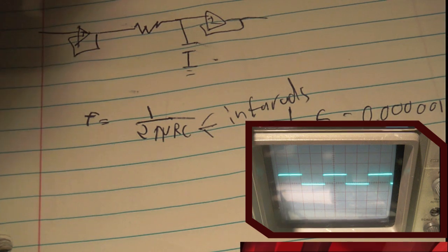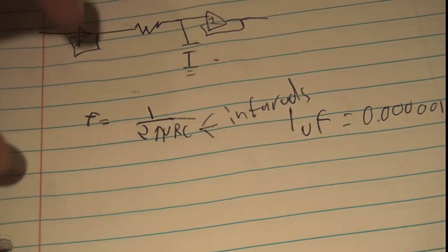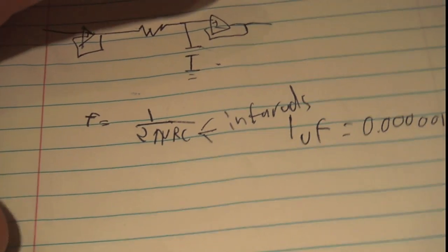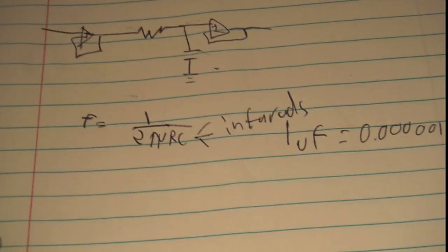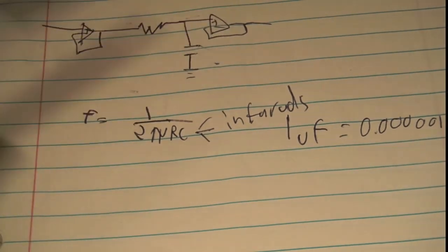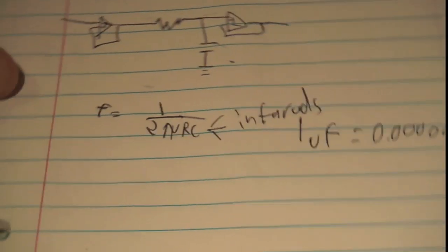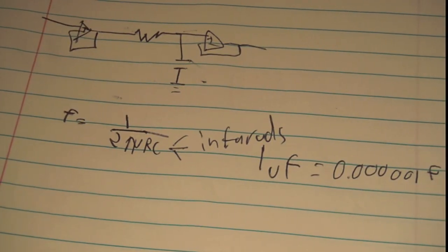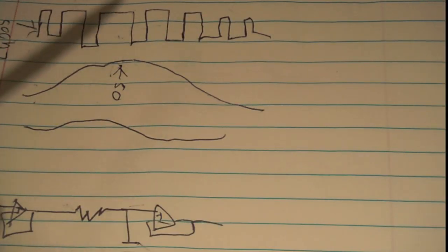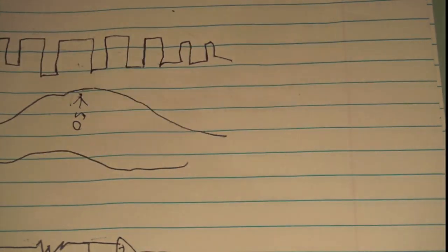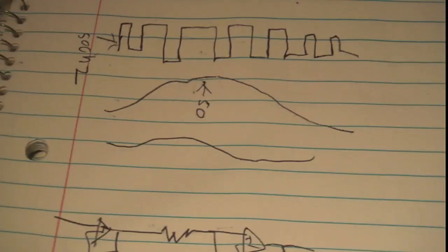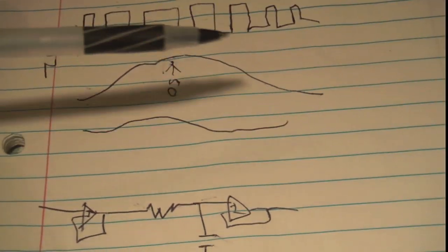So, I mean, that's very low. That's unnaturally low for a PWM signal. So that's going to make our job a bit tougher, but it's going to mean that I'm going to have to design better low-pass filters. So this probably won't cut it, but we'll see, okay? So we know that on our output, the higher frequency, in this case 500 hertz, 490, we'll round it up to 500 just because we like even numbers in electronics.